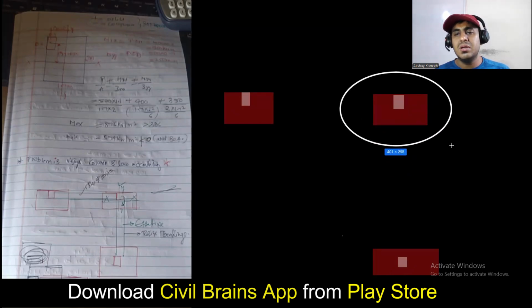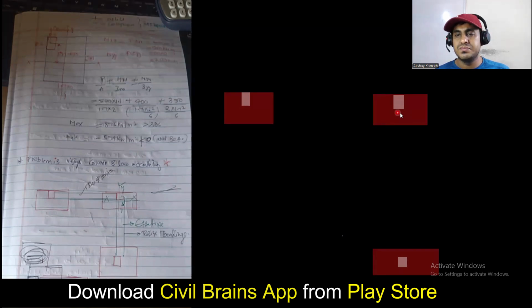So now you tell me, for this particular column, or for this particular footing, in which direction I need to connect the beam. See, it's eccentric only. It's eccentric because your footing CG is here, the column CG will come here, so it's not matching. So it has become an eccentric column, eccentric footing. But what is the advantage? Here the eccentricity is only in one direction.